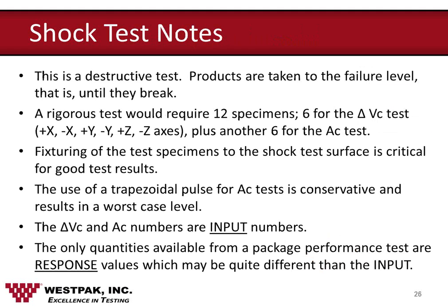There are some interesting notes that should be understood relative to shock testing. First of all, this is a destructive test. Products are taken to the failure level in order to determine their fragility. It's also interesting to note that a rigorous test would involve 12 specimens.